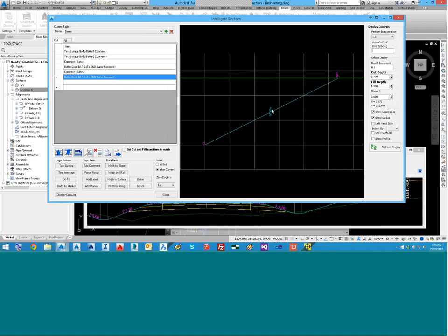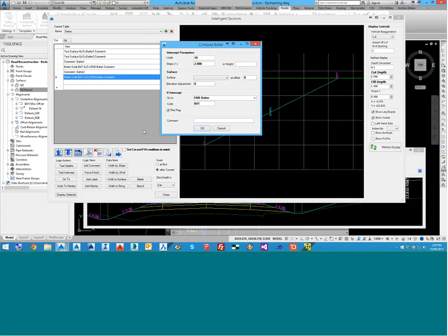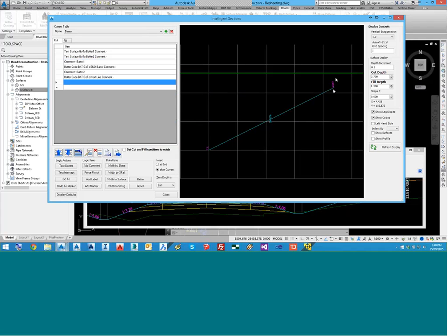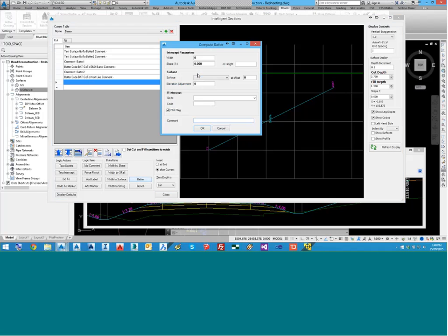What I could do very quickly, on batter 2, is say something like, I want this section to form to the surface, maybe 0.5 below the surface, and then go to the next line. And then you can see here that that code just finishes up half a metre below the surface. And because I said go to next line, I could add another batter in. So I could say batter at, say, 1 to 4, and if you intercept the surface and the batter, I'll call it bat1.